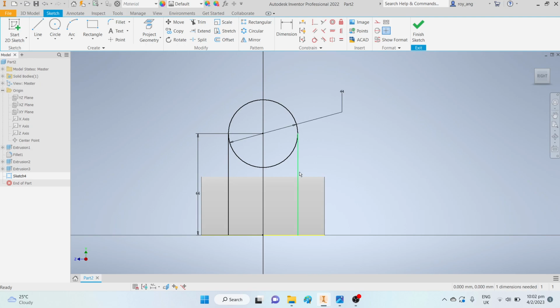So if this is blue, what does that mean? Blue means you can actually move it around and manipulate it, right? That's what it means. So one of the ways in which you can constrain, especially for lines like this that they didn't handle, was the tangent.